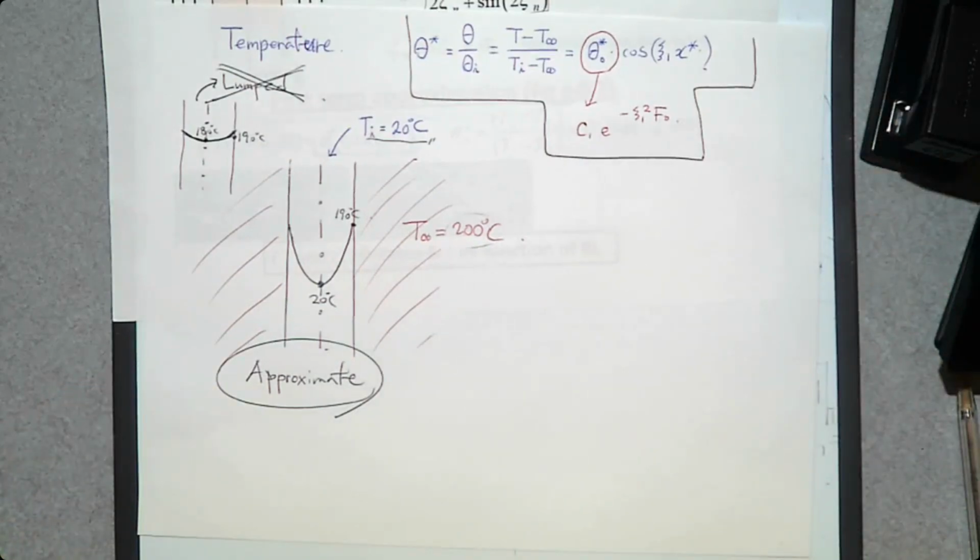But when you want to study how the temperature of the solid changes, we are not actually interested in the temperature near the surface. When we design an engineering system, our focus is going to be the critical point when the temperature is the lowest or the temperature is the highest. So in this problem, the location where we are interested is going to be the center line, right?